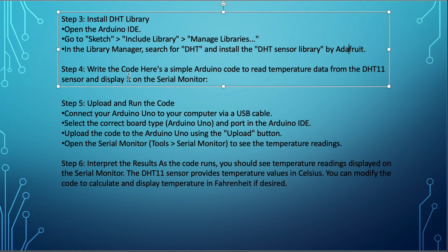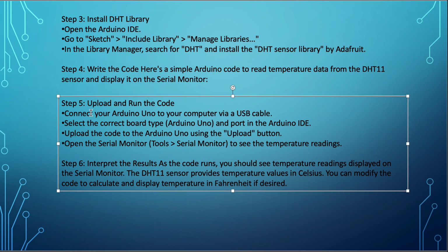Step 2, write the code. Here's a simple Arduino code. So we have the Arduino code for the sensor. Upload the code, connect your Arduino to your computer by USB, select the correct port, then just run it.